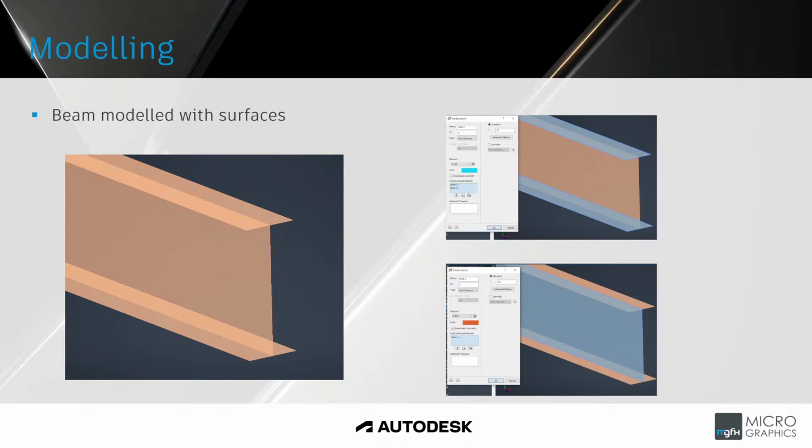On the right-hand side of the idealizations, you'll see that the top two surfaces have a thickness of 10, and the middle one has a thickness of 6.3. So I'm getting more accurate results because my thicknesses are more accurate. They're the exact ones and not an approximation of the three surfaces or idealization that I've created.